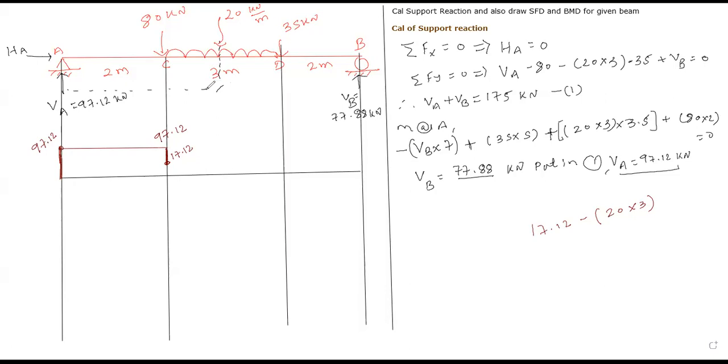Bhargav, right? Yes, right. I want more answer. Rethink, we are considering the shear force diagram. You have given me the answer for bending moment diagram. I want more answer. Okay, inclined line. Please keep in mind, if there is a uniformly distributed load in between 2 points, your shape of shear force diagram will be an inclined line. So we simply plot an inclined line between C to D.